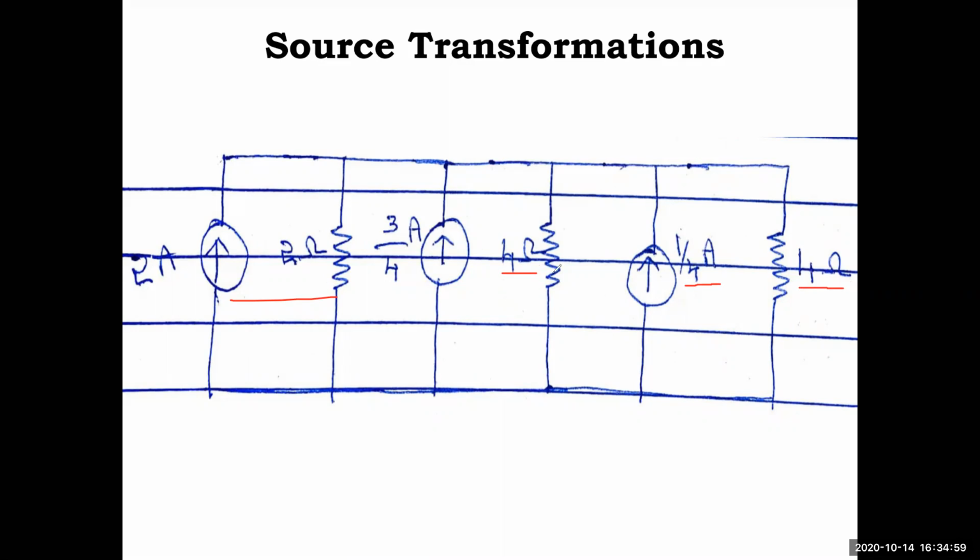Okay, so 3 current sources are there, just as first problem. Just add up all the 3 current sources, and there are 3 resistances in parallel. Use the elements in parallel. Okay, so resistors in parallel formula and calculate this. So here current source easily you can calculate. 2 amps, 3 by 4 means 0.75, 1 by 4 means 0.25, both together it is 1, plus 2, 3 amps. So current source you are going to get 3 amps without any calculator help. Then you calculate the resistance, so that will be shown in next step.